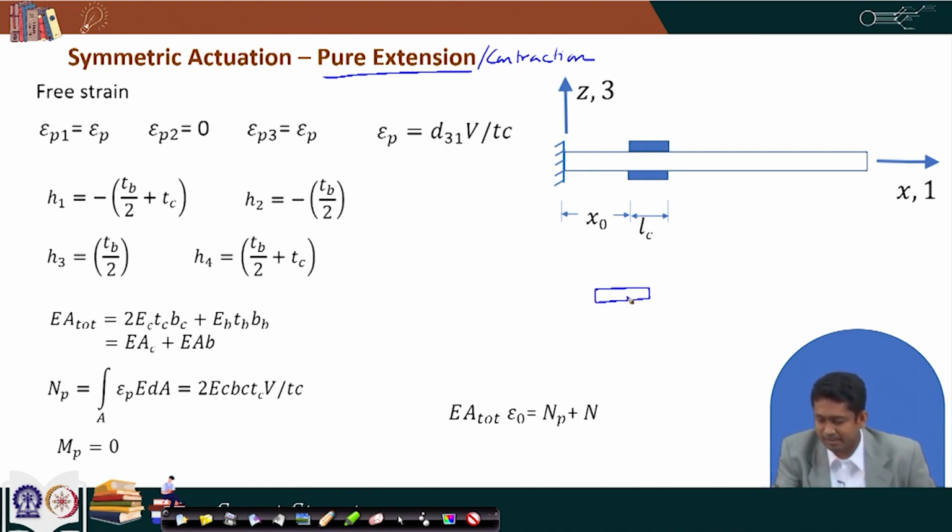Now, what do I mean by similar manner? To understand this, let us see here. Suppose we have a piezoelectric patch here, this is our direction 1, this is our direction 3. Now, it is polarized in direction 3. So, suppose it is polarized in this direction. To have this kind of polarization, the poling voltage must have been applied in this form, then only the polarization direction can be this.